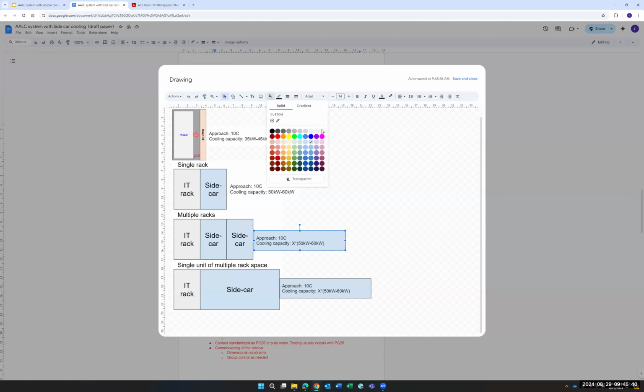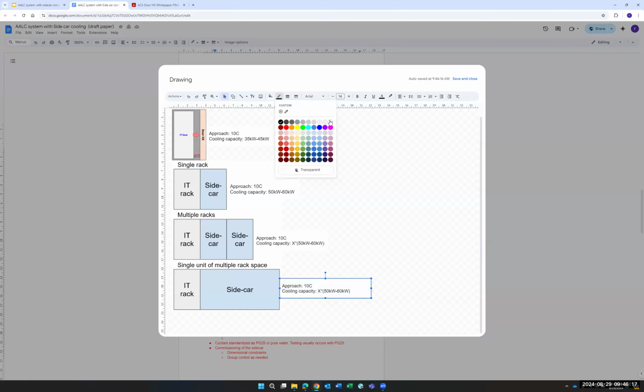It could be, and at the same time, its efficiency will also be a little bit different from others because now you have one type of radiator or heat exchanger in this, right? Because you are limited by the width on the depth. Now, if the width is not a concern, they can have literally a single heat exchanger or two heat exchangers that might be of a different width and different depth. That will change the efficiency of the heat exchanger and also the overall solution. Yeah. Does that make sense?